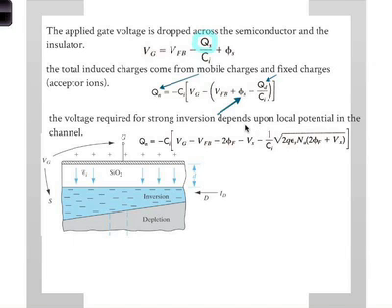Yes? I just wanted to make sure, I'm assuming that they're getting QD from equation 6.32 in the book, but there it uses phi F instead of... Yes, it's a good question. Instead of phi F, I don't really know. Because there's a local potential here. The bands bend differently across the channel. So if you look at the channel, the width of the depletion region depends upon how much reverse biased the substrate is with respect to either the drain or the source.